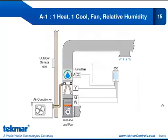Now let's look at our first application. This is a one heat, one cool with fan and relative humidity control application. So we have one stage of heat that's coming from our furnace, and that's going to be operated with the W relay. Our fan will be operated with the G relay. We have one stage of cooling here from the air conditioner. That will be operated with the Y relay. And our accessory relay will be set up to operate the humidifier. We could also set that up for a dehumidifier.